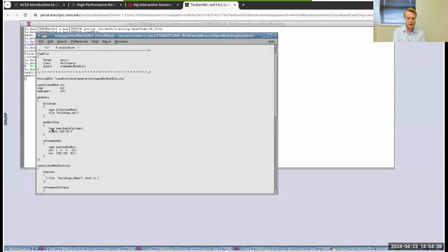this is the bottom, kind of center of the tower. So z equals 0. And then we'll define the top of the tower, 0.2. We put that at the same x and y, so the tower is vertical. But let's make it 225 meters tall. Quite a big tower. Okay, so we have now defined a geometry for this new building.